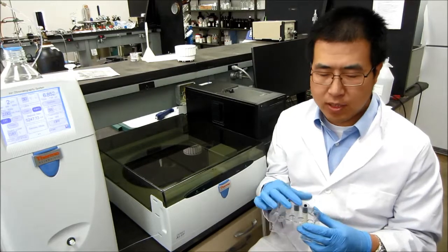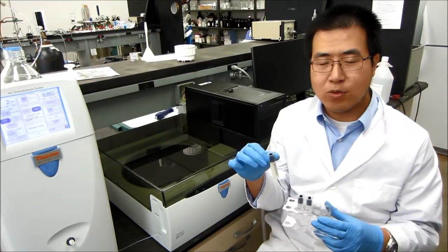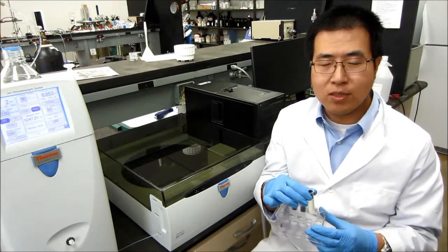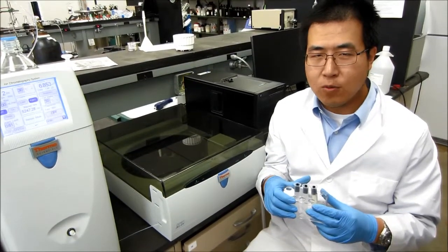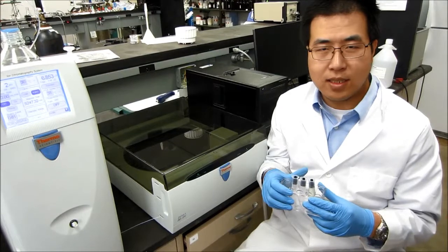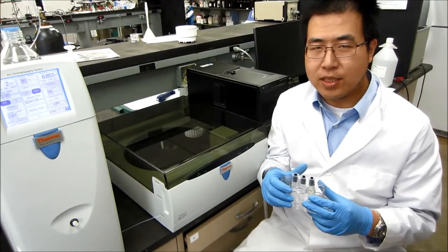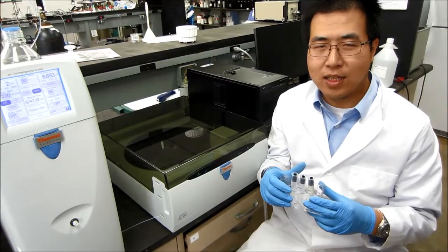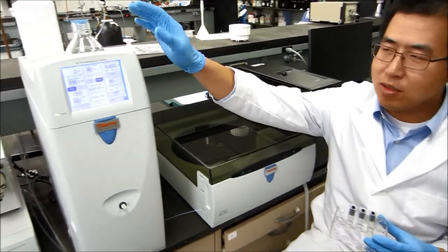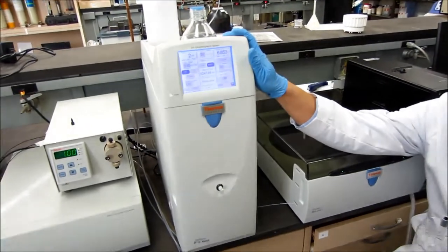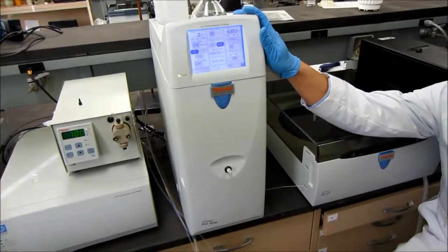The samples will be extracted into these 5 ml aluminum solution vials. Chromate will be analyzed using NIOSH 7604 method, while the other inorganic oxides such as nitrate, phosphate, sulfate will be analyzed following NIOSH 7900 method. The ion chromatography with the conductivity cell has a detection limit roughly about 0.1 ppm.